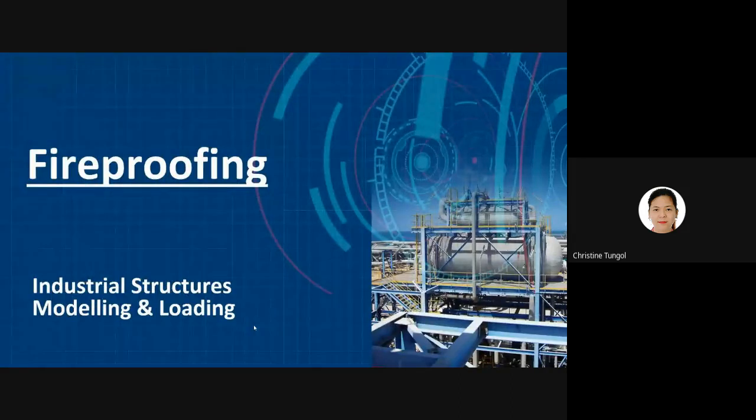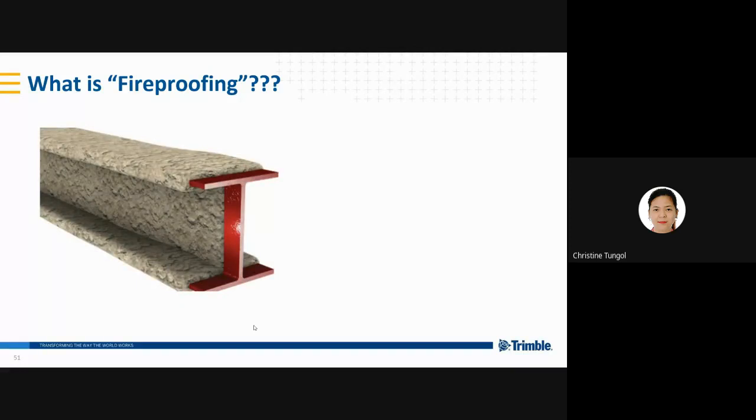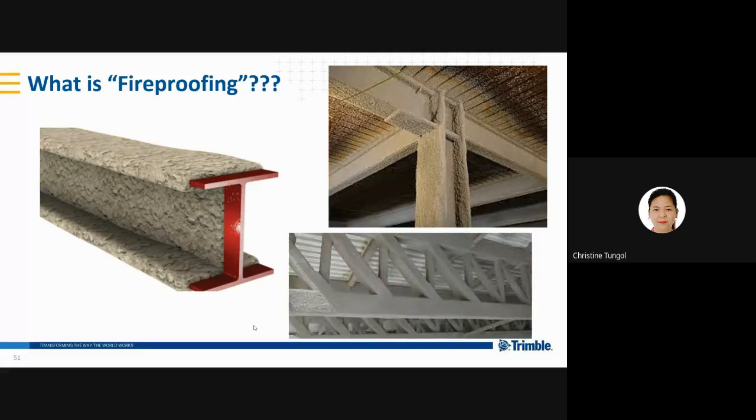So the next enhancement is fireproofing. Fire protection can now be specified in the analysis and design model by the user. Fireproofing is the application of fire-resistant material on the surface of structural members in the form of protective paints, thin or thick film coatings, sprays, and fireboards. Tekla Structural Designer gives the facility to apply a surface coat to a member, defined by thickness and density. This is useful for open structure wind load, where wind load is acting on a large surface of the member.